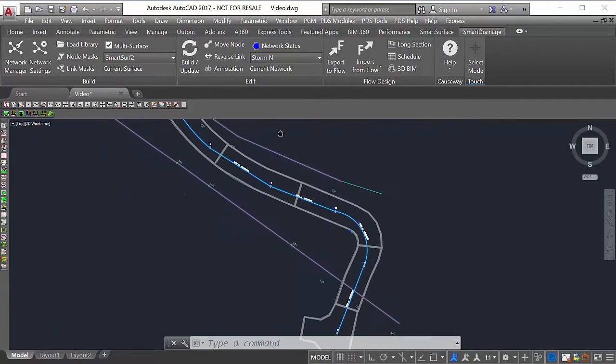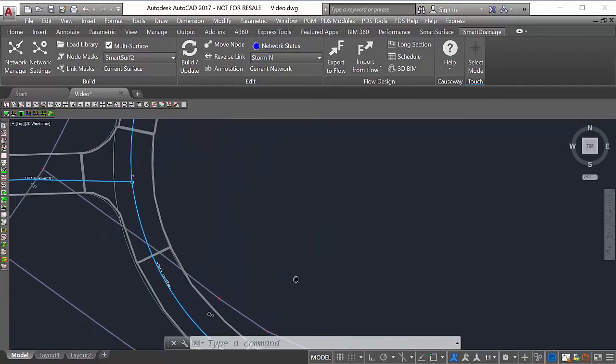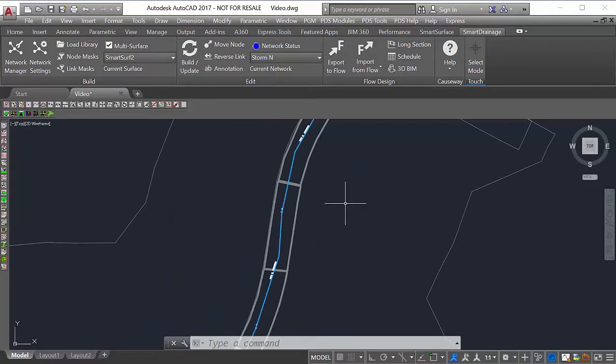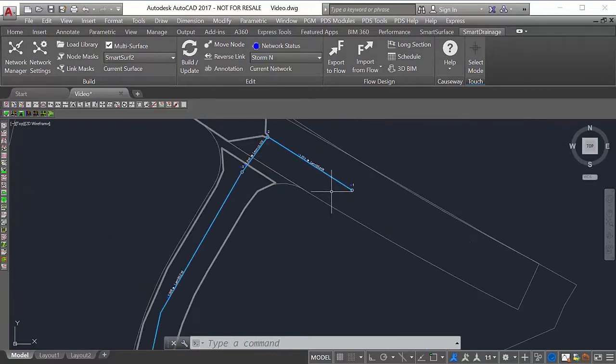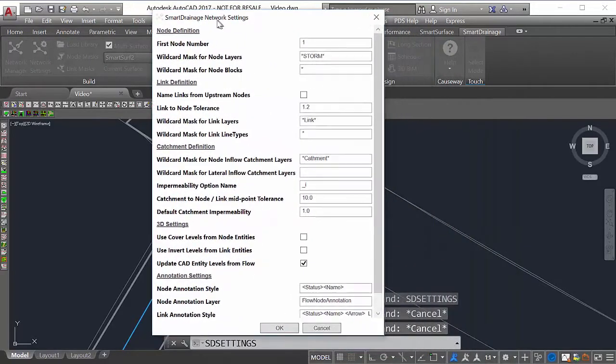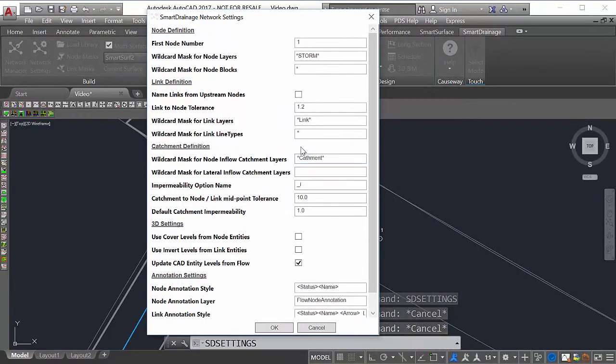Polylines are the most versatile entity to describe the planned route of links, especially those that are not straight, such as ditches or those following the alignment of roads. It is the user's responsibility to ensure that the chosen pipes can be laid to the curvatures or bend angles drawn. Blind or curve-fitted polylines are not currently supported.